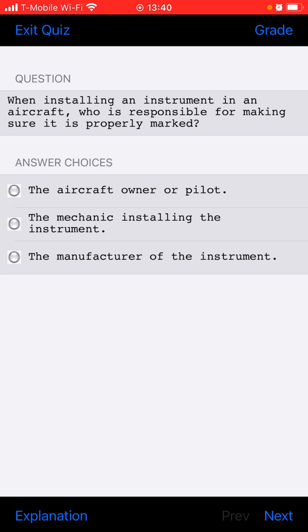Let's continue. For what reason is a fuel jettison system usually divided into two separate independent systems, one for each wing? To help maintain lateral stability by jettisoning fuel from a heavy wing if necessary.